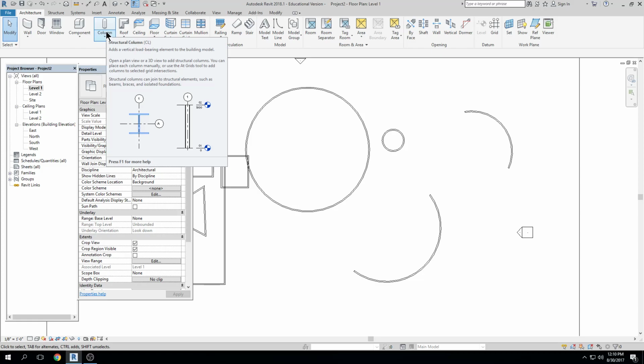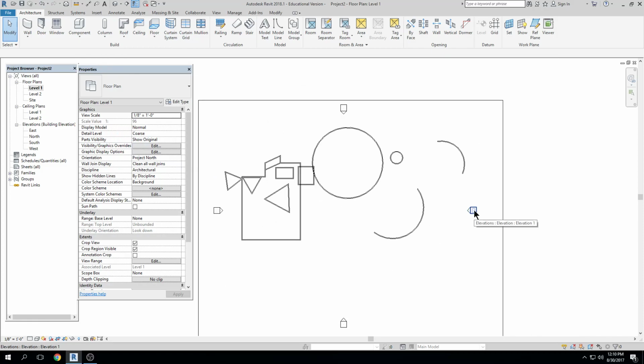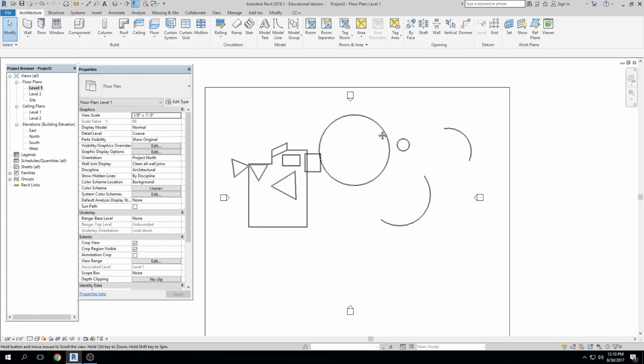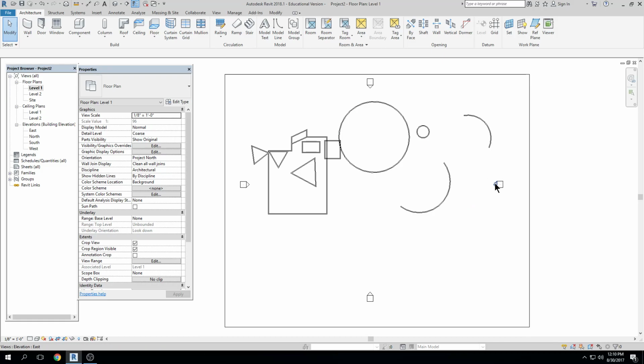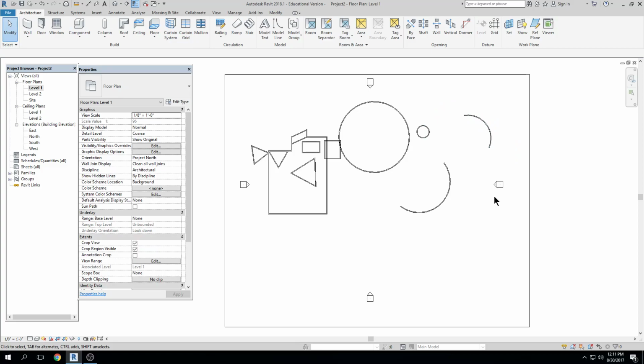I have some questions. So you see how you kind of drew within those little markers? Does that matter? Okay, let's talk about what will happen if you do that. You're talking about these, right? We'll talk about these a little more in depth, but Ellie is asking, my lines are kind of outside of these little markers, what happens? Well, these little markers are elevation markers. Items that are seen in front of them will be shown in elevation, and items that are beyond them won't be shown.